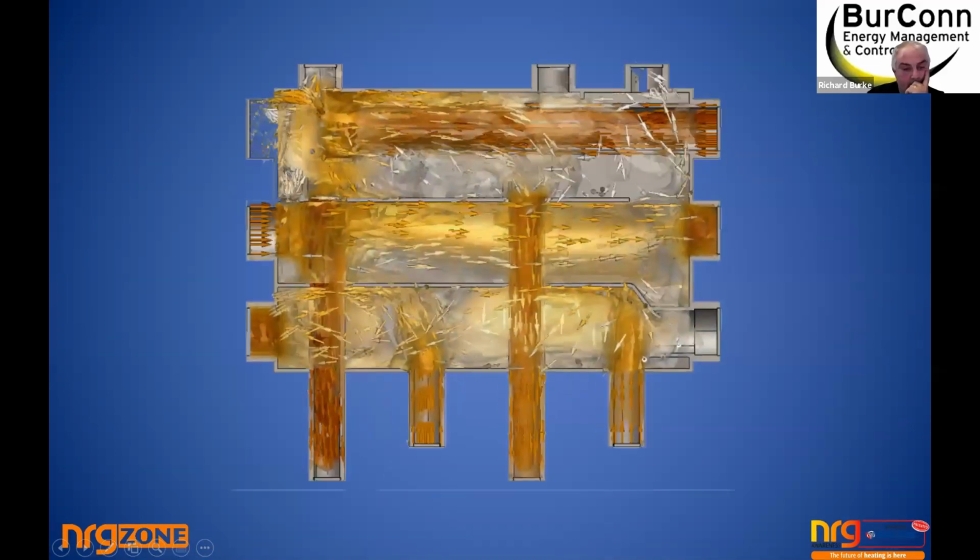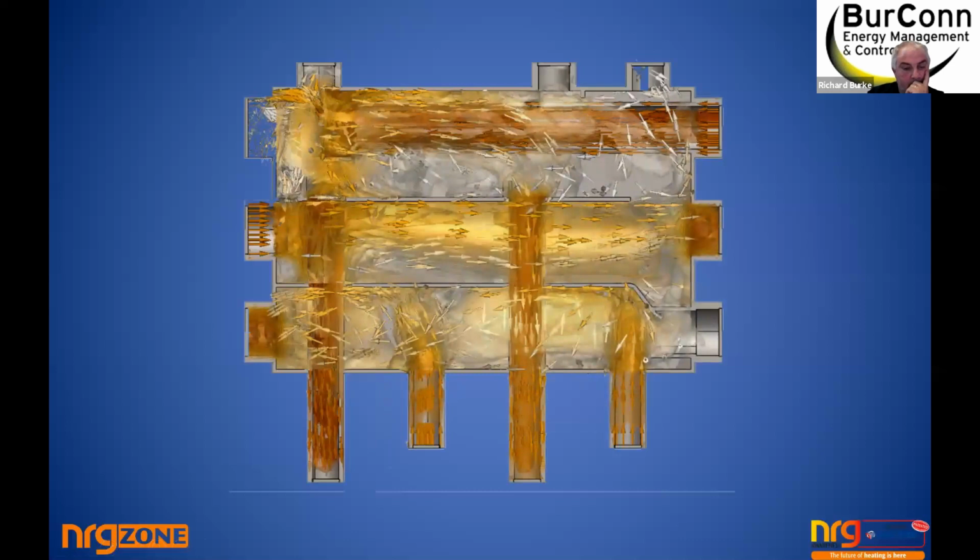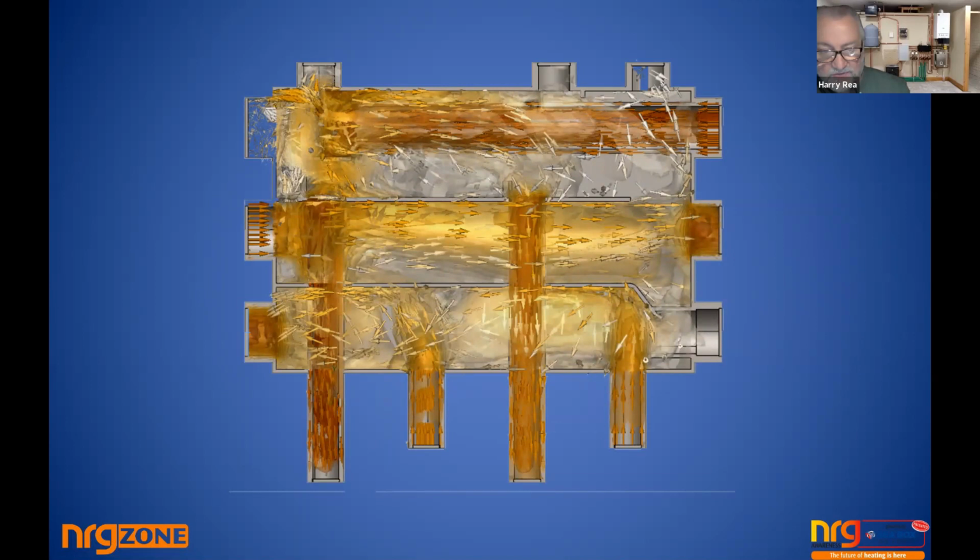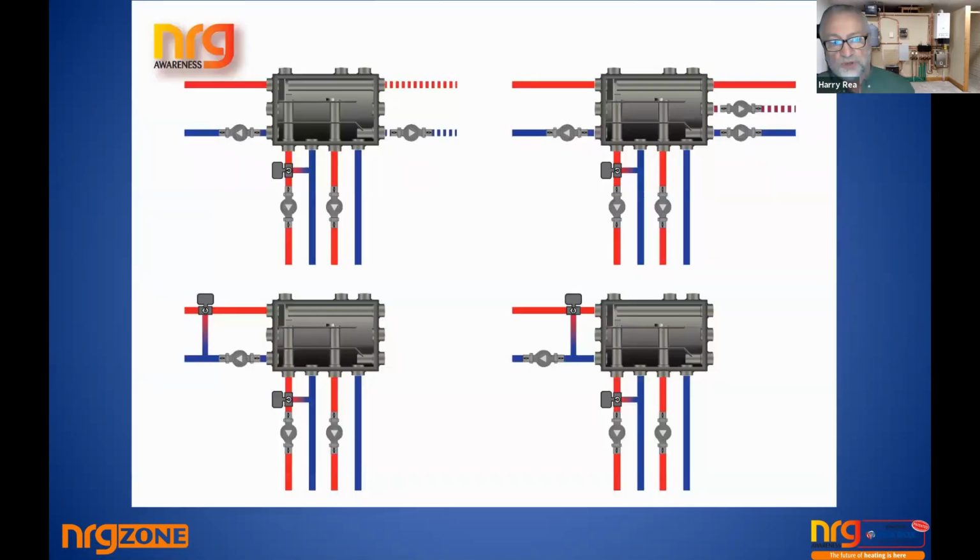You can see what's happening inside. The cylinder's taking away the high temperature here, and the heat pump is carrying on its work rate, and so is the gas boiler. So if you decide to use mixing valves, there's utterly no reason why you couldn't put a mixing valve on a given zone and not on the next zone, or vice versa.